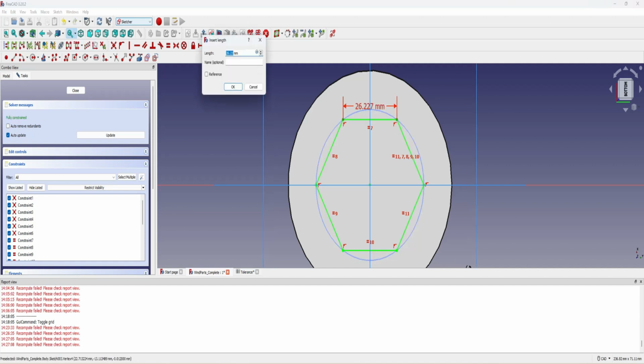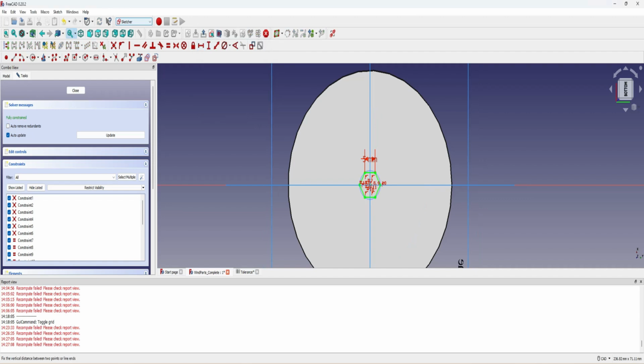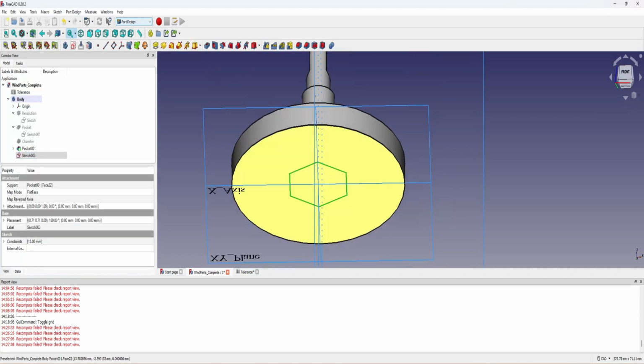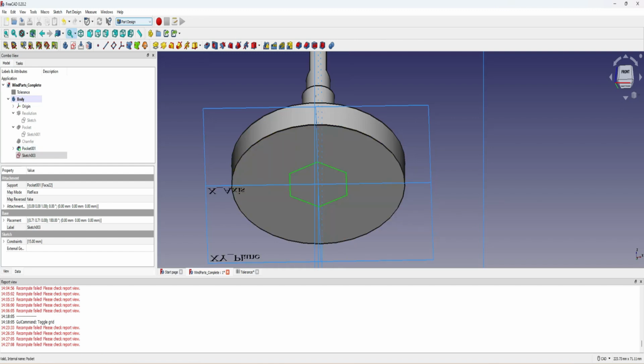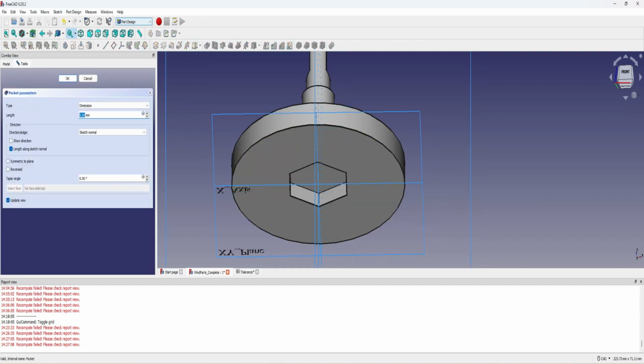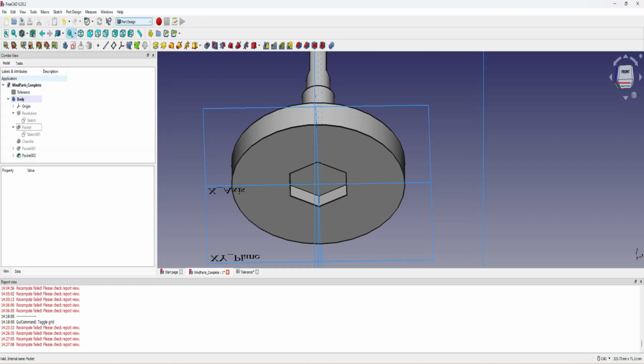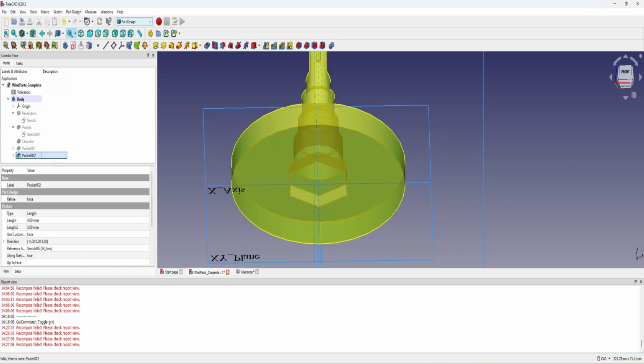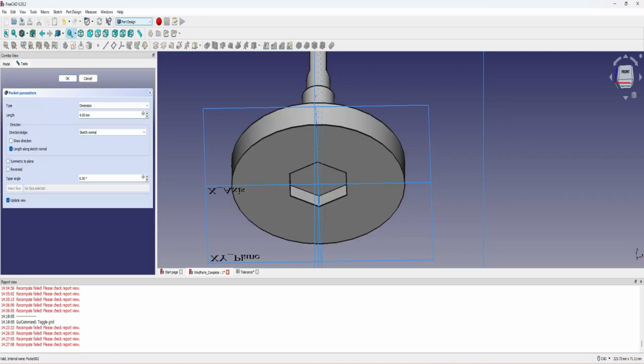The reason for that is because whatever I attach to the face plate of this component, it's going to be hard to 3D print it correctly on a 3D printer without a bunch of additional material to hold up anywhere there might be spaces or gaps in the actual part. So here we just make the octagonal shape, use the pocket tool, bring it in a few millimeters, and then that'll have to be broken out once I 3D print the part, because I'm going to put this bottom piece that I'm working on right now on the build plate and 3D print it going up to the very tip